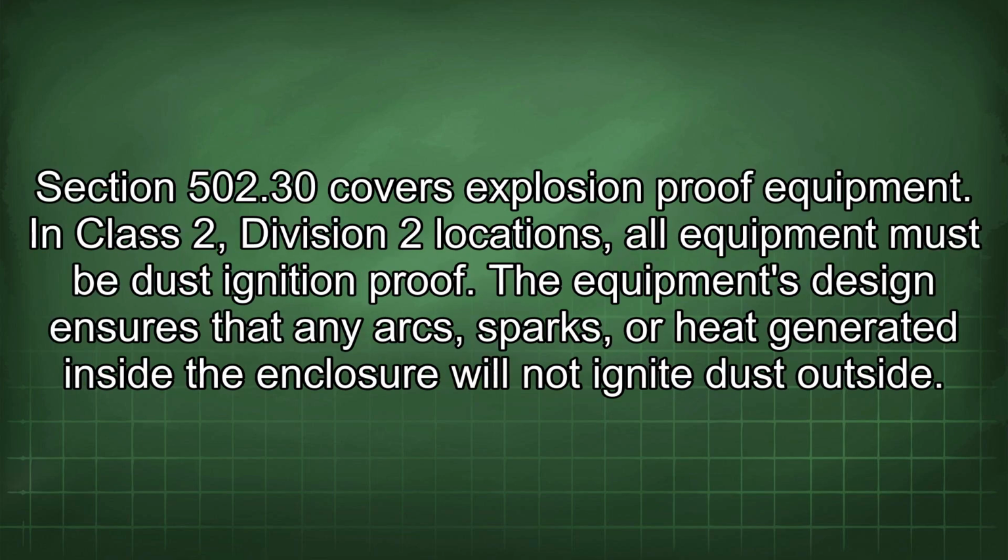Section 502.30 covers explosion-proof equipment. In Class 2, Division 2 locations, all equipment must be dust ignition proof. The equipment's design ensures that any arcs, sparks, or heat generated inside the enclosure will not ignite dust outside.